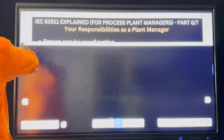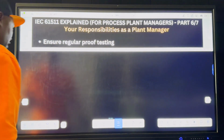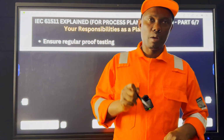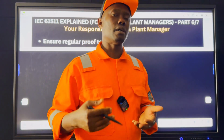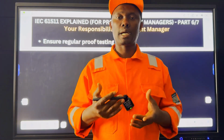One of the responsibilities as a plant manager when it comes to functional safety is ensuring regular proof testing of your safe loops. In your SRS document, that's your safety requirement specification document, there is a section where you will find the proof test interval. This same proof test interval is part of the parameters we use in calculating the PFD average during the SIL verification process, okay?